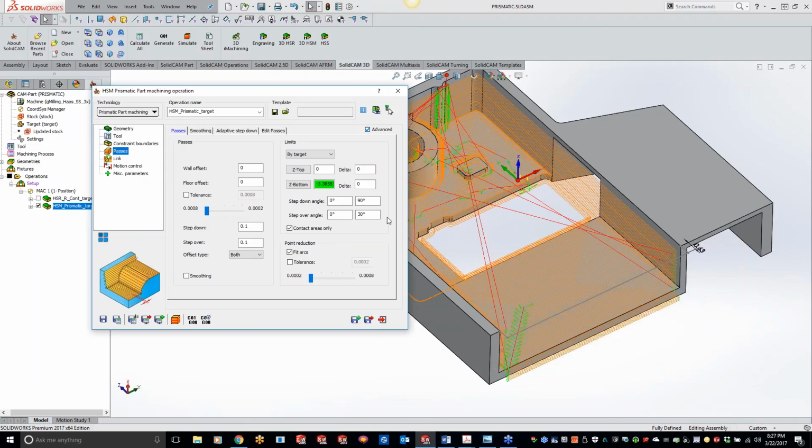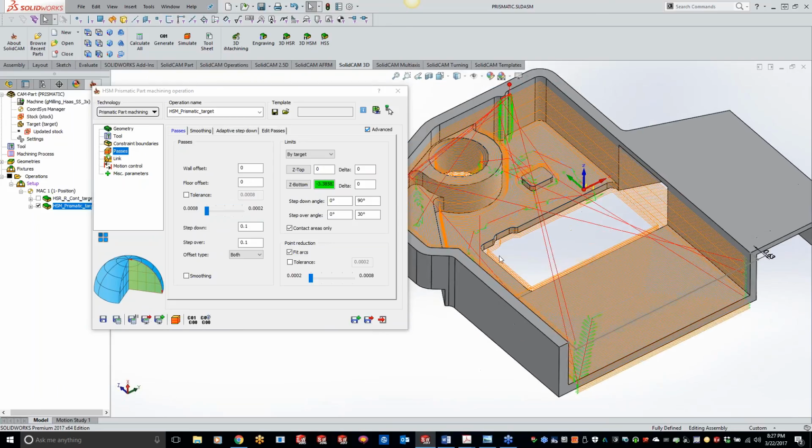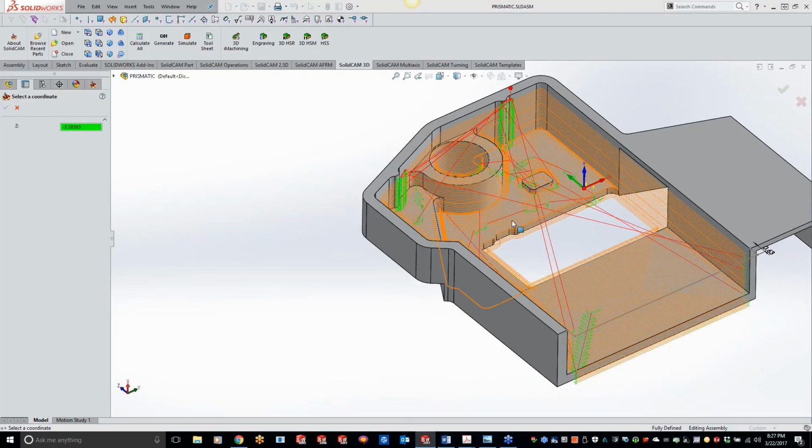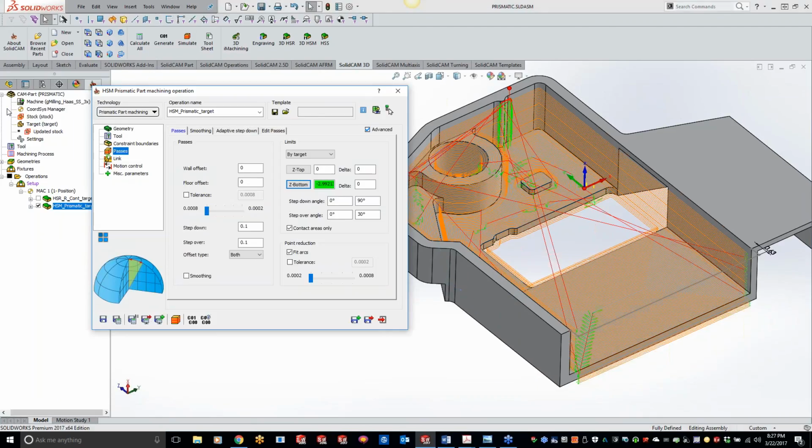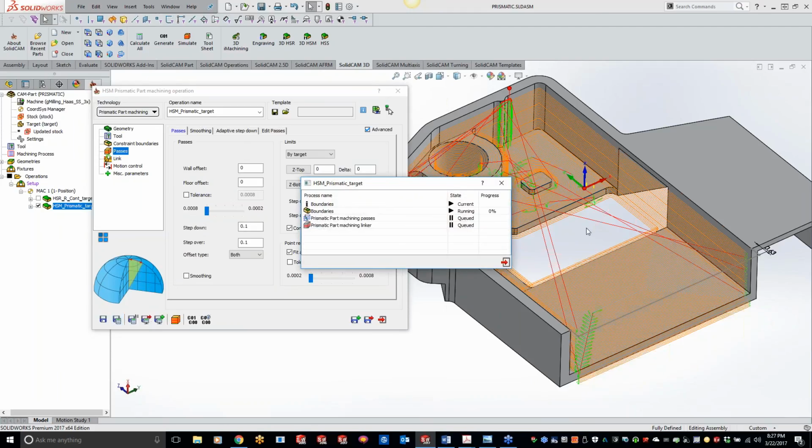No, Jordan, what I did is I actually picked the bottom of the part. So right now I'm at 3.3 here. If I pick the floor right here, this is the lowest it's going to go. So now if I do save and calculate, I can't zoom in while it's calculating, but it's going to avoid hitting, if you can see my mouse cursor, basically these walls right here, and anything below that, it will not go now. Perfect. Yep, he picked it up.